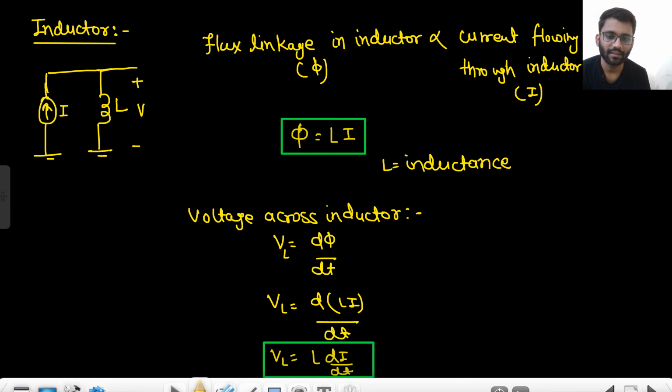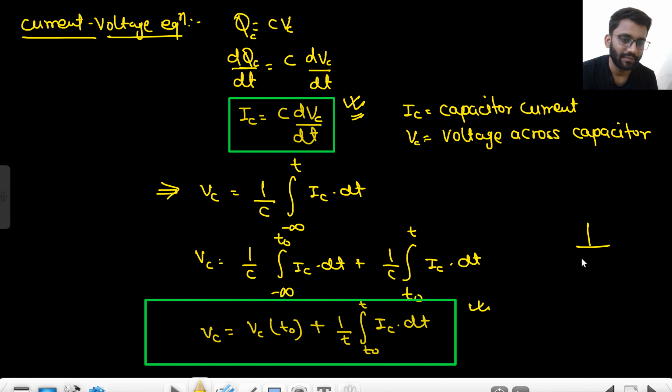And in case of the capacitor, if this is the capacitor and this is the voltage across it, okay, forget about the voltage, it will come later on. This is the capacitor and the direction of current is this. So in what direction will the voltage be developed? In this direction. If the direction is this, then positive upward and negative downward. So in case of inductor and in case of capacitor, current will always flow from high to low potential. Okay, but in some cases the current can flow from low to high potential as well, while discharging.